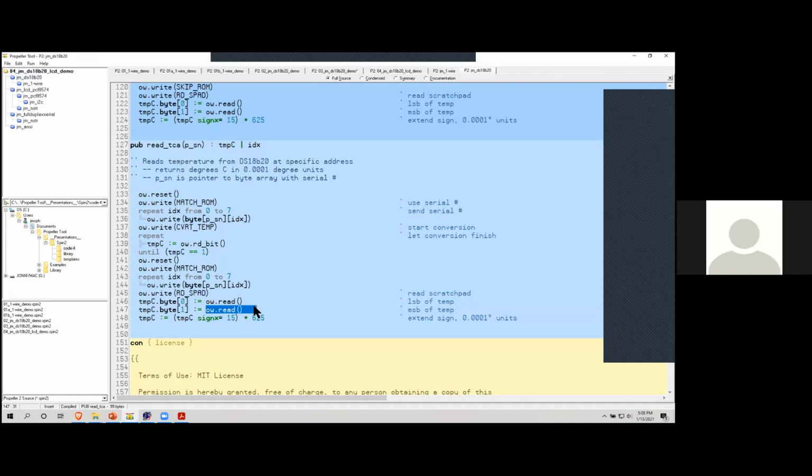John, I ran into the same problem that you did once using these, and it's very difficult to read multiples on a single bus. But the beauty of the Propeller chip is that you've got 28 or so spare pins, and I just put one device on each pin. You can do that. Now in the P1, I have to use a cog because of the timing requirements.